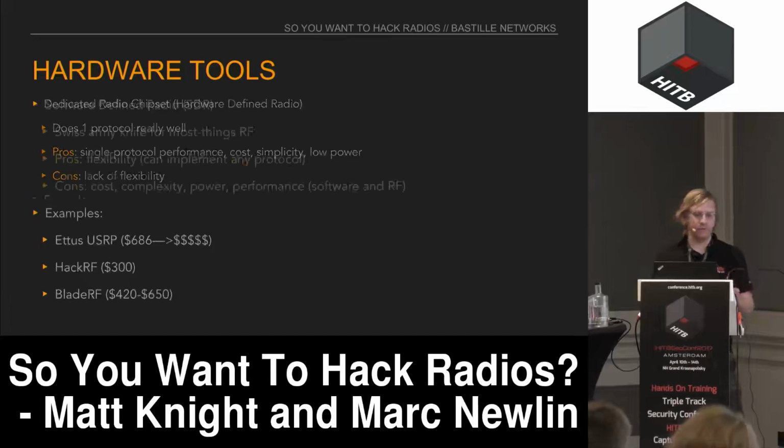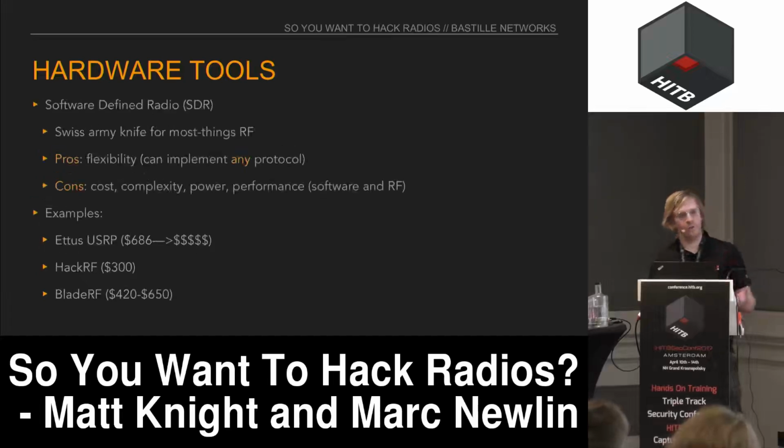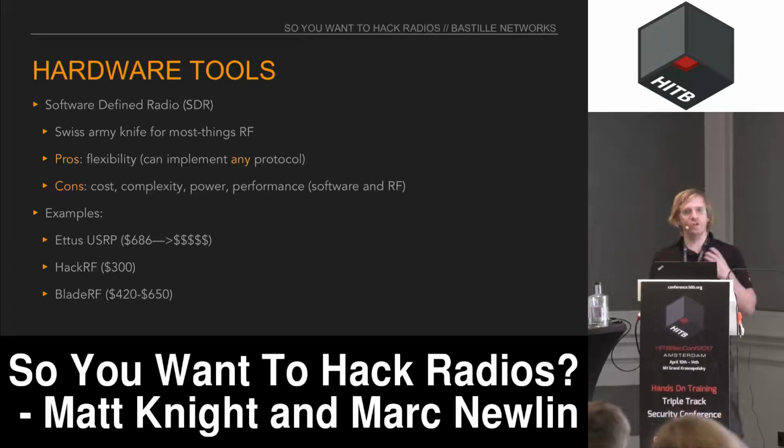Then on the software-defined radio side, the big difference between an SDR and an HDR is that an SDR can be reconfigured on the fly. You can tune it to different center frequencies, you can set different channel bandwidths, and instead of the logic that makes it a Wi-Fi radio or a Bluetooth radio living on the hardware, it sends the raw radio data to your host computer or an FPGA, and then the logic that makes it operate on a specific protocol lives in software.